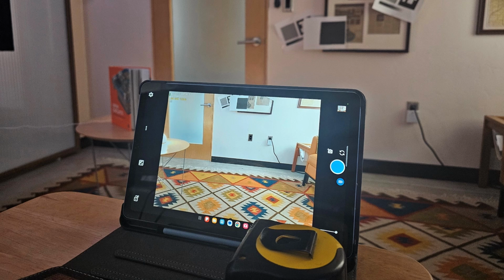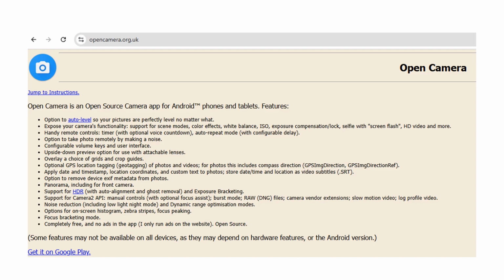You can look both at edges, and then a lot of times you can also look at resolution features in the target to see what's happening to different kinds of features. And these ideas of periodic features are popular because then you can directly measure MTF by looking at the response to a periodic signal. Newer cameras may or may not allow you to sample raw data.